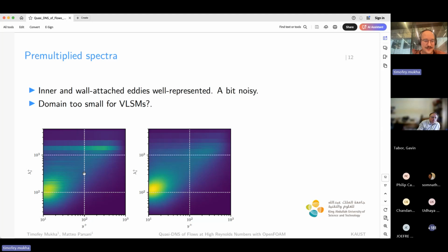And if we go to the LES results from OpenFOAM, we see that in principle everything is captured pretty well except for these large-scale motions. And I think that's where my presupposition about the domain size being a little bit insufficient comes from. That maybe they're so very large that they didn't fit in my domains, so you got some aliasing effects, and we would need essentially to increase the domain size to get the spectrum properly in this upper side of this plot.